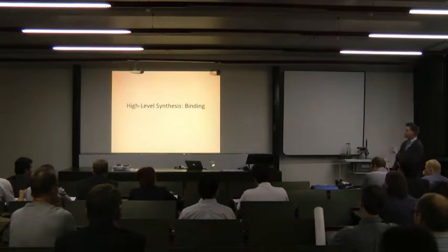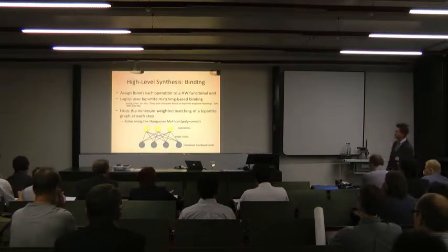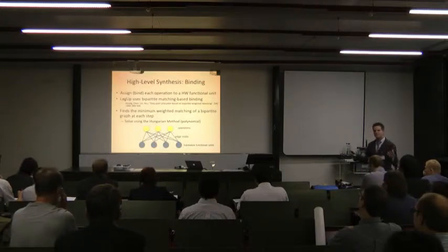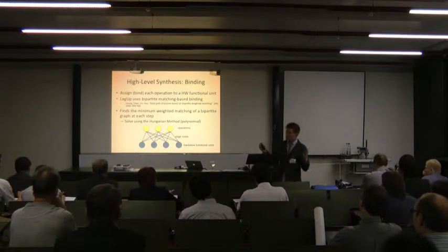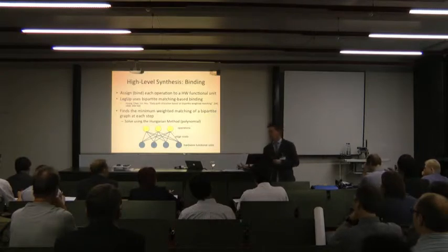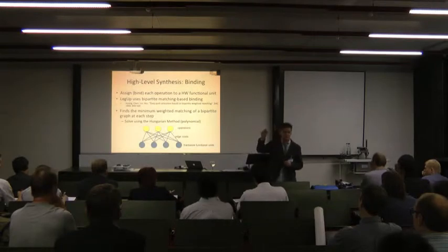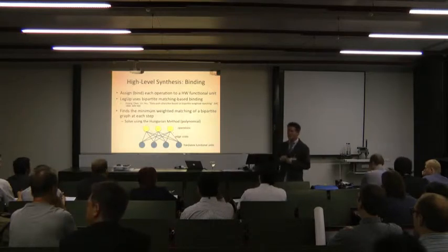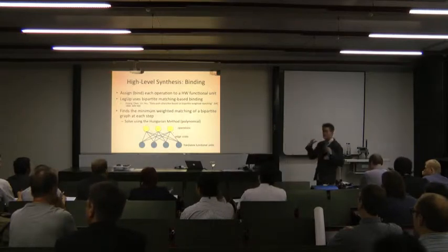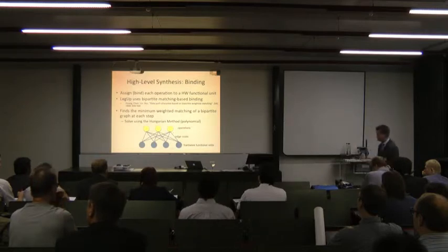Now, last thing I'm going to say about high-level synthesis before I dive back into what we're doing in LegUp is just want to talk a little bit about binding. That's another key step in high-level synthesis. With binding, imagine a C program where I had, say, 10 division operations. But let's say in my hardware I only have 3 divide units. I have to take each of my 10 division operations and assign it to one of my 3 divide units. I have to bind it to one of my 3 divide units. And that is called binding. That's a step in high-level synthesis.